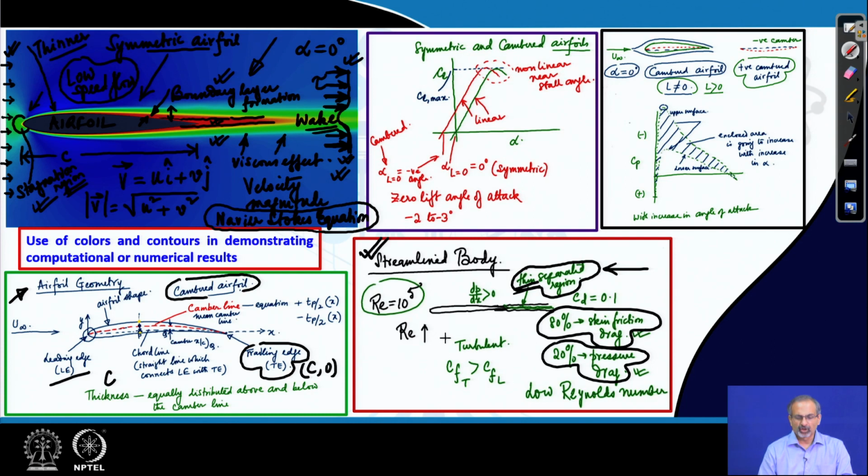Again, we do not know precisely what kind of Reynolds numbers are involved here in this flow. So, if the Reynolds number is comparatively large, then this flow could also be a turbulent flow. And then we know from some brief calculations that we did on a flat plate that the skin friction coefficient would be larger in the case of turbulent flow compared to laminar flow.